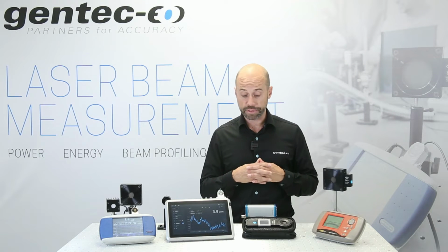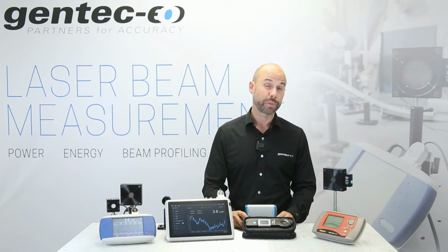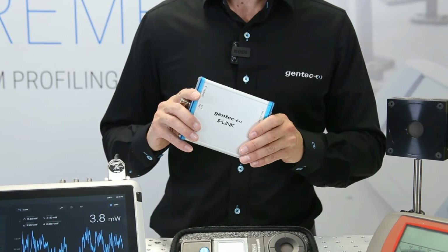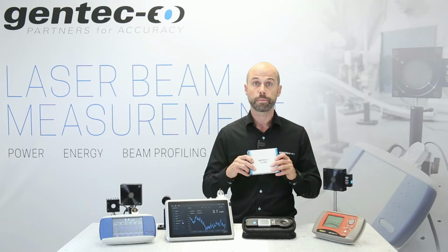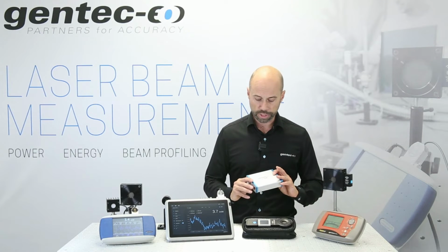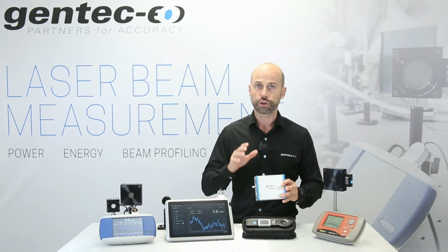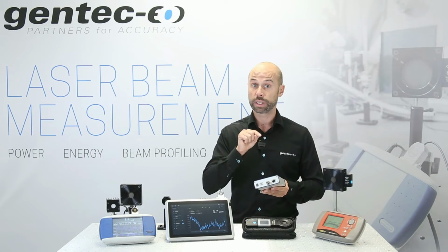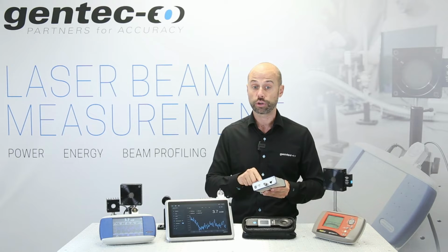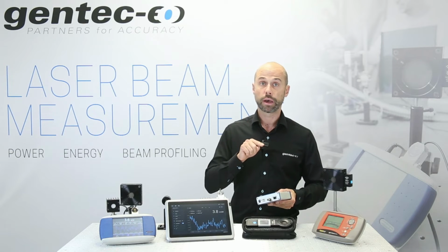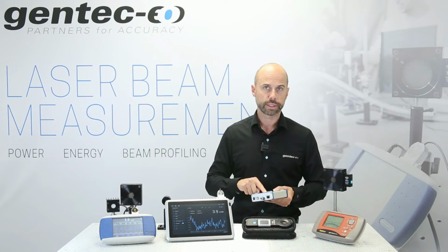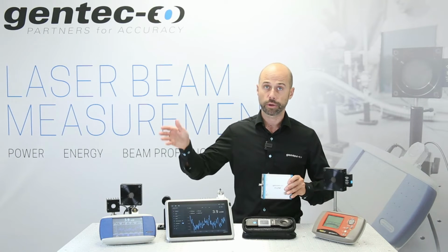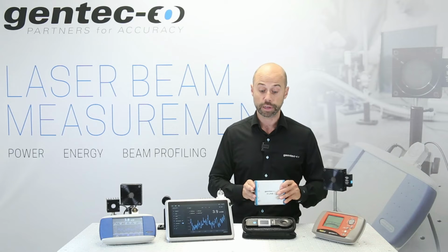Then what we have next are not displays, but we call them monitors or interfaces to computer, which are pretty much all packaged in a box of different sizes. This one is the S-Link, which is the solution that you need to take when you have an energy meter and you want to connect it with Ethernet. So this is the solution you need for a fail-proof 24 hours, 7 days, month, years solution that you want to monitor over a very long distance, since Ethernet does not have a limitation on the cable length.